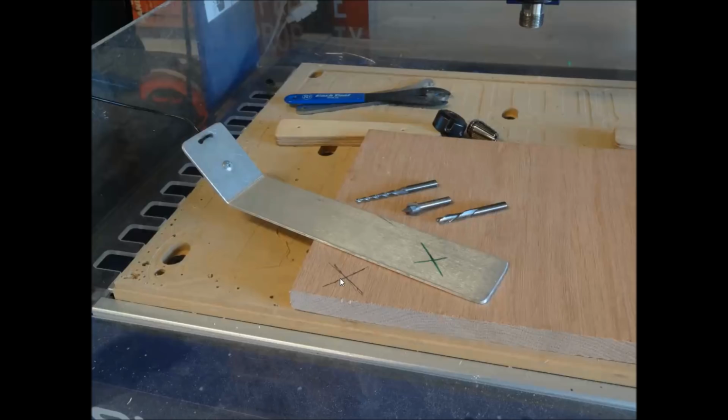We can do it with the keypad and have a memorized location, but every time you change a bit, if you do it on the same portion of that material, it's going to alleviate any discrepancies that you have with material thickness. And same thing with the zeroing plate.